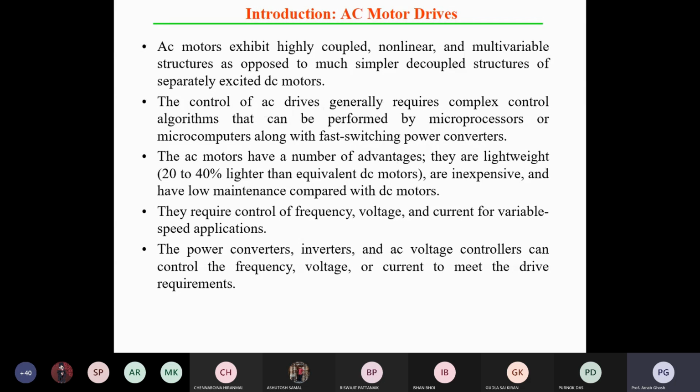That's why you did that comparison, and you can use the same thing again for the power converter, the power electronics converter. So the duty will be developed by your controlling signal. From the duty you can control the switches of your power electronics circuits, or power electronics converter. As per the change in the pulse width of the switching logic, you will definitely get different outputs, meaning variable outputs as per your requirement, as per the closed loop requirements.